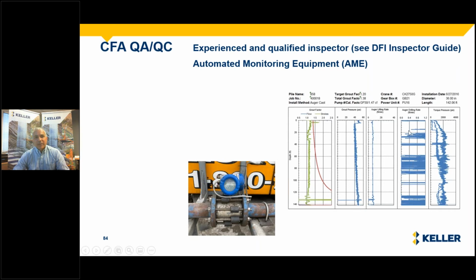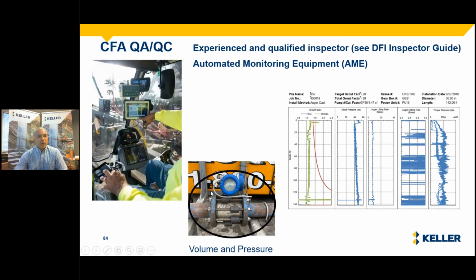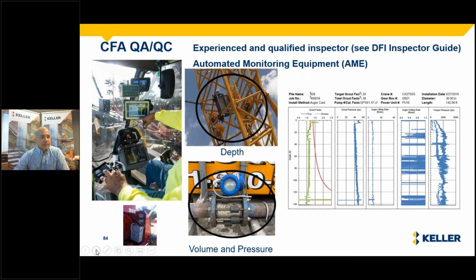Now, one important aspect is we can measure more or less the speed of installation, and we can correlate this speed of installation to the soil report. Are we going through hard soils or soft soils? All that has, of course, computerized systems in the cabin where the operator can see them and be guided to know if he's doing a good job on that pile or has to recast. The same can be seen by an inspector on the site as everything is transmitted via Wi-Fi or Bluetooth.